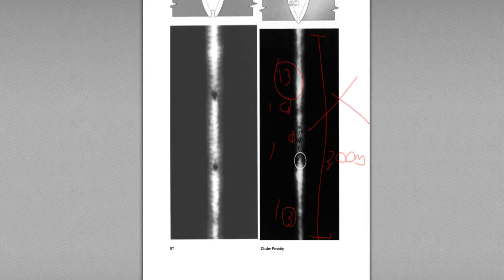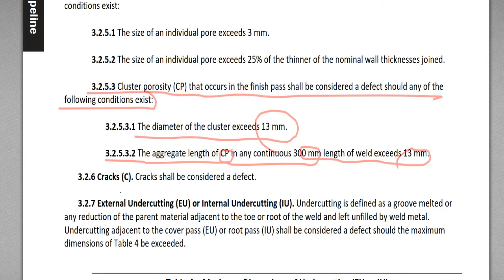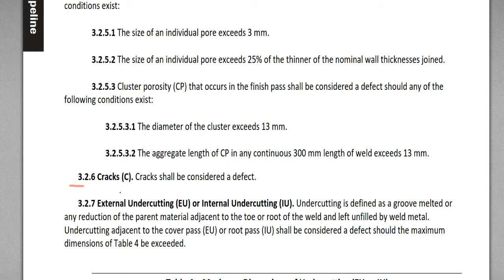That's reject. And 3.2.6, cracks. A crack shall be considered a defect. If you see a crack in the weldment, wherever and whatever, that's reject.